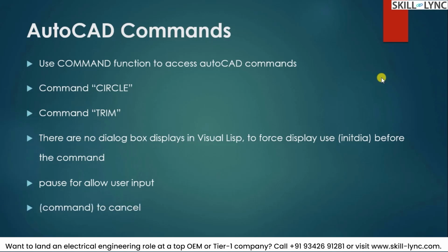And likewise, when you type in command within parentheses, AutoCAD understands that it has to come out of the previous command that is within it. So these are the basic AutoCAD commands that we are looking at. That is, first, putting any variable name preceded by command means that all the textual characters that follow have to be treated as AutoCAD commands, and it has to look within its library to execute. So that is the function of command, space, double quotes, and the AutoCAD command within.